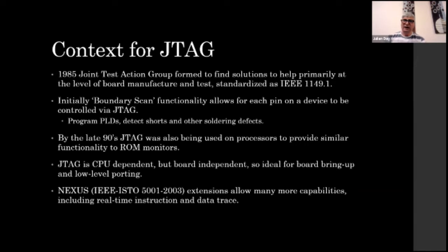So the first use case they had for this was they wanted some way to do what they call boundary scan, which is effectively being able to control each of the pins on a device independently, so that you could check: are they shorted, are they soldered properly? But beyond that, you could actually use it for programming PLDs and such things. Again, if you connected to a microprocessor, you can potentially control all the address and data pins and clock data onto your bus as well. So it's quite powerful in terms of what they came up with.